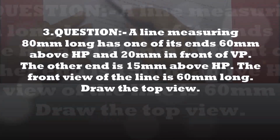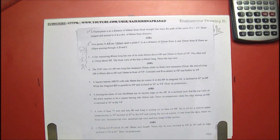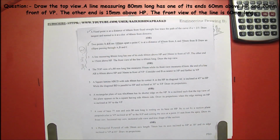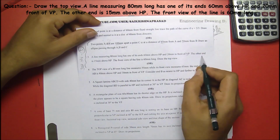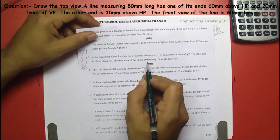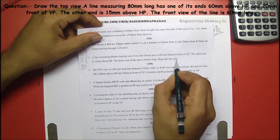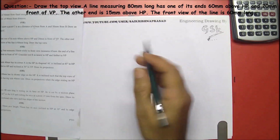We are going to discuss set 3, third question. Let me read out the question for this. A line measuring 80 mm long has one of its end 60 mm above the HP and 20 mm in front of VP. The other end is 15 mm above the HP. The front view of the line is 60 mm long. Draw the top view and get the required data from the question.